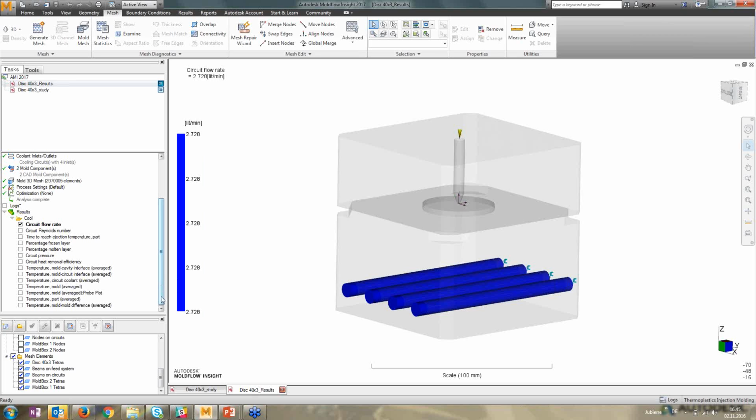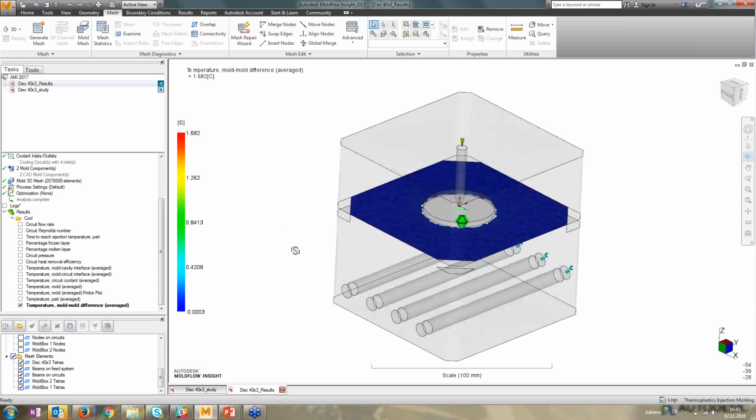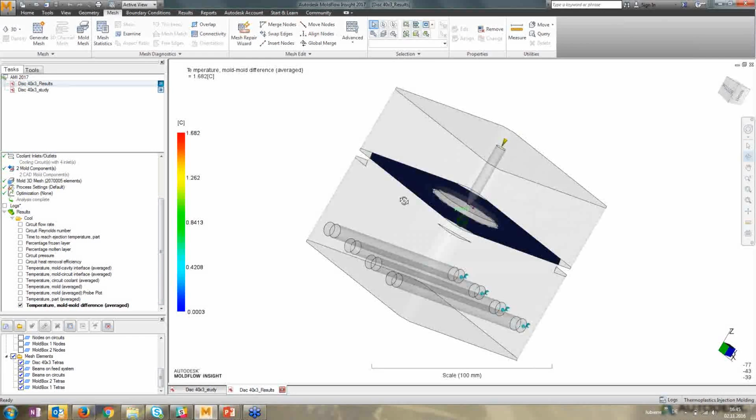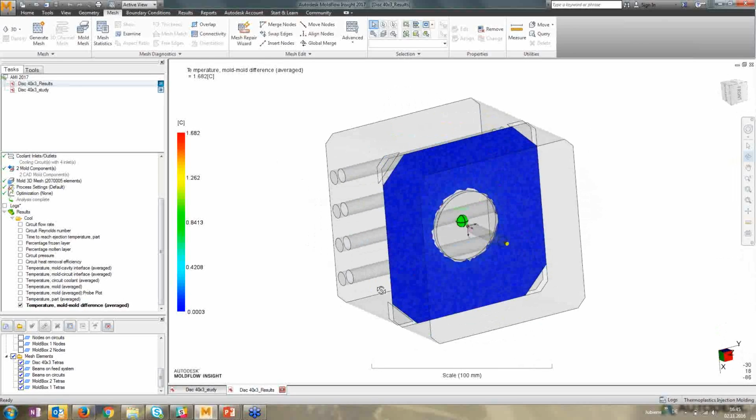One of the plots that we usually don't get, and because we defined move and fix we have it in this simulation, is the temperature on the parting plane, on the work plane that is defining the two different moving parts. And we could see how this temperature is defined. Quite a nice result that is not possible in boundary element methods, and if we don't define this moving and fixed, probably we also would not get it here.